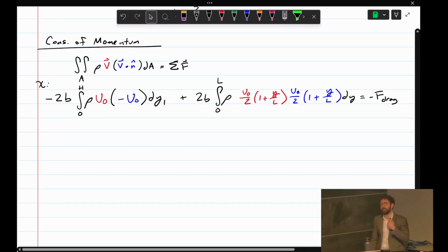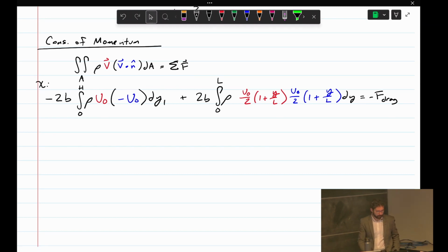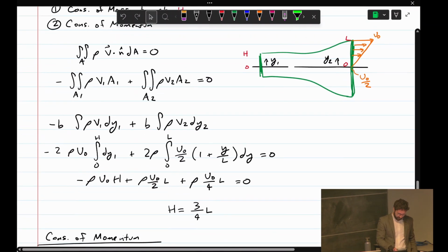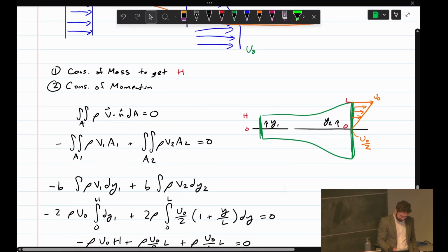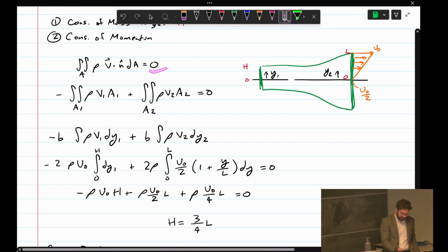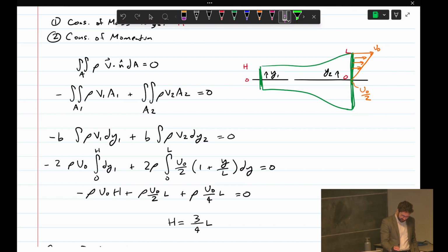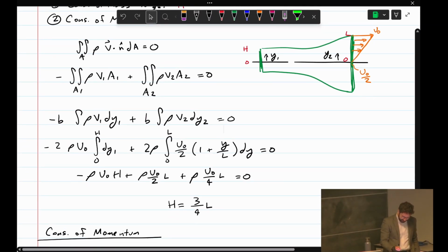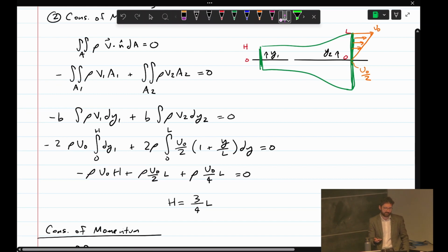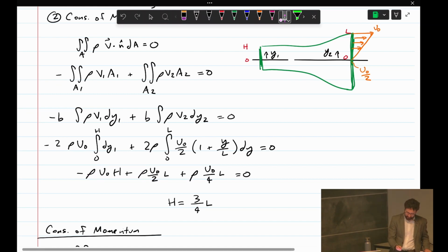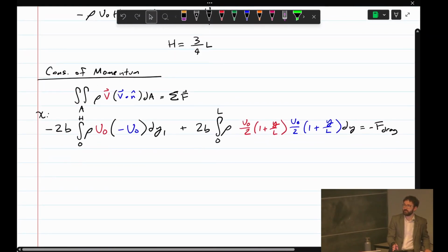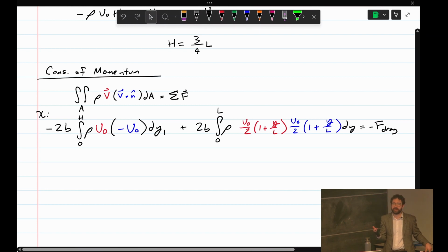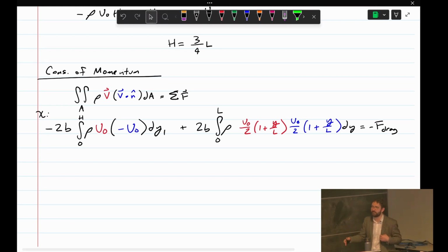So any questions here? Because it's equal to 0 on the right-hand side. So on conservation of mass, it's equal to 0 here. So the b, sorry, yeah, maybe I don't have a 0 in this line. So the b is, yeah, we can just pull the b out. Same thing with the rho. You'll notice, because we have uniform density, the final answer doesn't actually depend on the density. Any other questions? So you're right, it's not going to go away. And intuitively, we don't expect it to go away. So the drag force, if you have a longer wing, you should have a higher drag force.